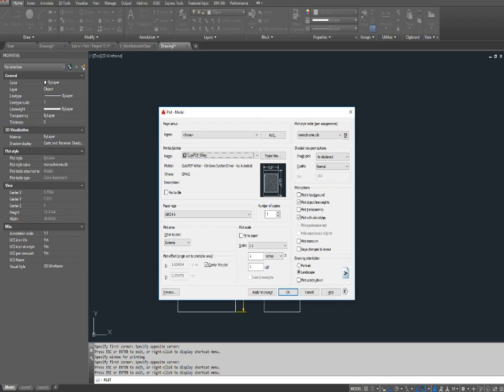If you're not sure what scale you need to get this at, take the fit to paper button, push it, see what number you get. 1 to 0.9143. Okay, great. That means I could fit 1 in there and it would just be a little smaller than what it wanted to print. And I can come pretty close.